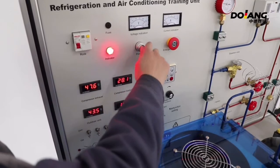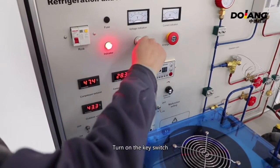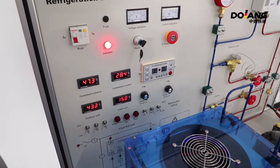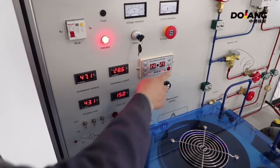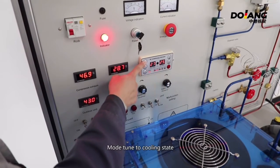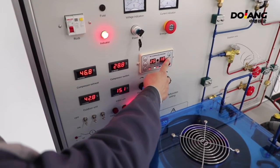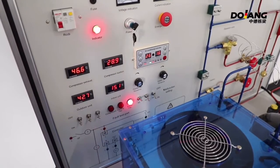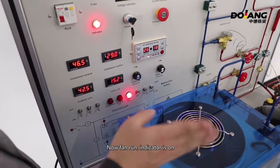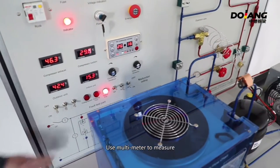Now do the fourth fault experiment. Turn on the circuit breaker. Turn K4 to off. Turn on the key switch. Turn on the controller. Turn the mode to cooling state. Turn the temperature to the lowest. Now the fan runs and the indicator is on, but the compressor doesn't start.